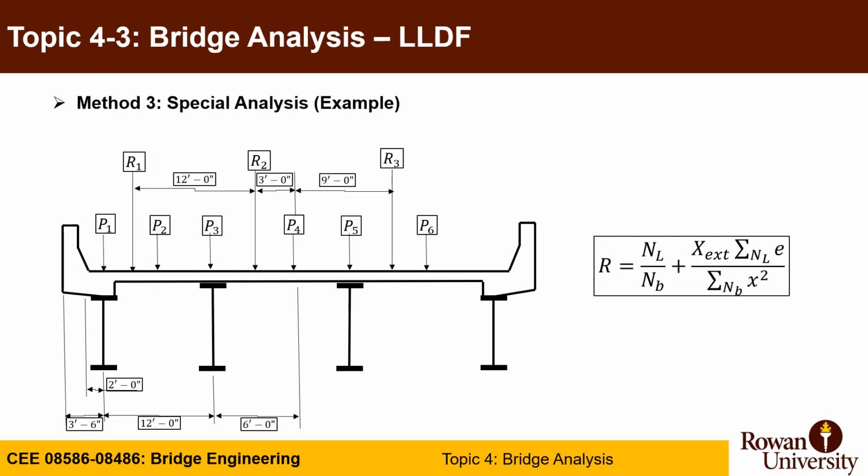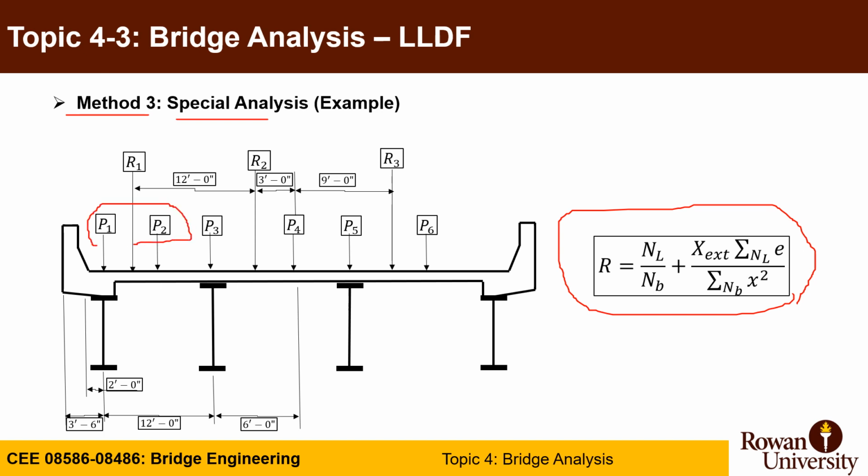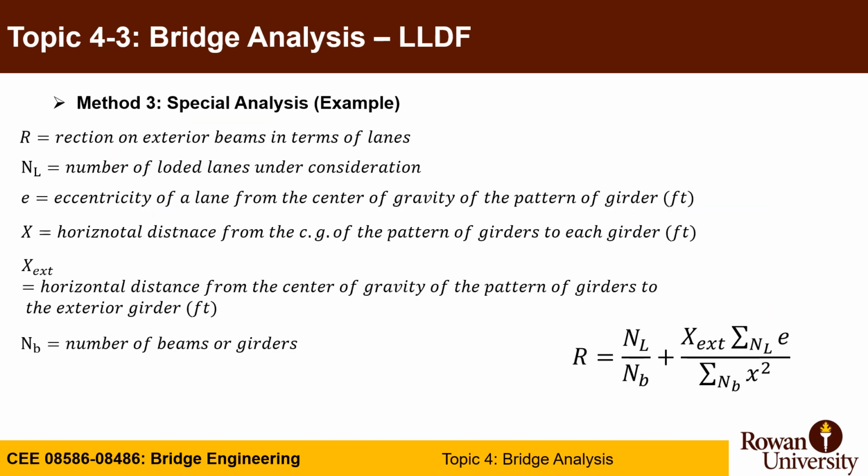The last method we will discuss here today is method 3, only for exterior girder, which is basically this set of equations. So in order to know the set of equations, for every truck you will have a resultant called R1, R2, truck 1, truck 2, truck 3, and all the distances between this resultant and the bridge superstructure. So a lot of terminology to unfold this equation.